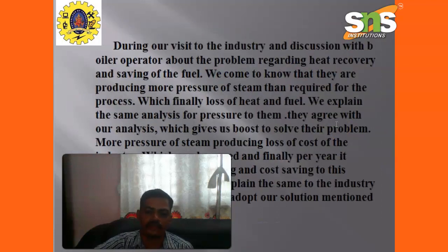During our visits to the industry and discussion with the boiler operator about the problem regarding heat recovery and saving of fuel, we came to know that they are producing more steam pressure than required for the process, which finally causes loss of heat and fuel.